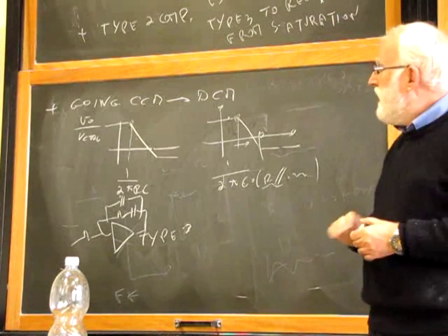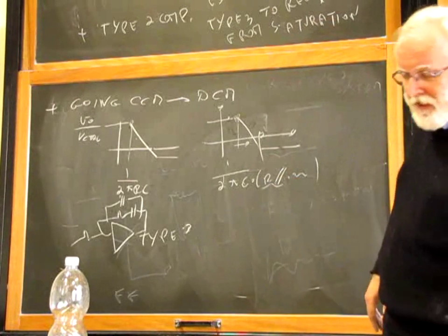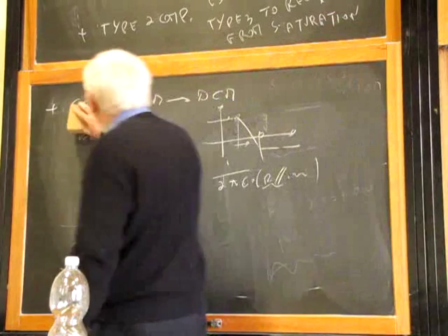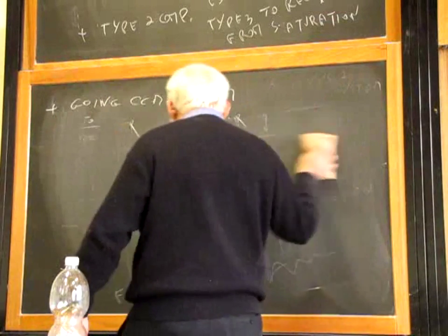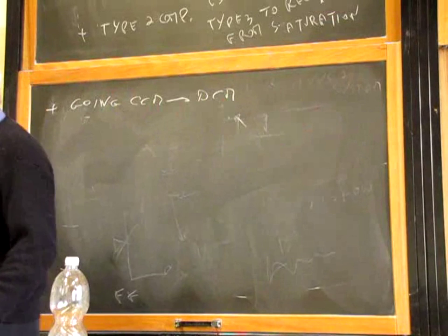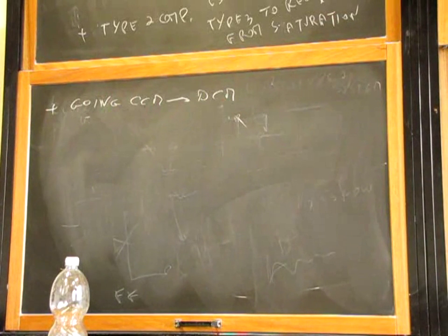Okay? There are more of these advantages. For example, if you want to put in parallel two sources, two power sources, can you just connect them in parallel directly? No. It depends on the kind of power source. If you have two voltage sources, well, you cannot connect them directly in parallel unless they have the very same voltage. If you have two batteries, either they are the same and they have all their lives together, or you cannot connect the two batteries in parallel directly. Two batteries can be connected in series, but not in parallel.